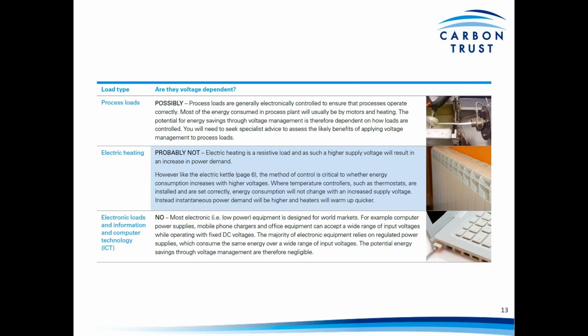Electric heating is probably not voltage dependent just because it's a resistive load. So higher supply voltage will result in an increase in power demand, but like the electric kettle example that we gave earlier, the method of control here is critical to whether the energy consumption increases with the higher voltage.